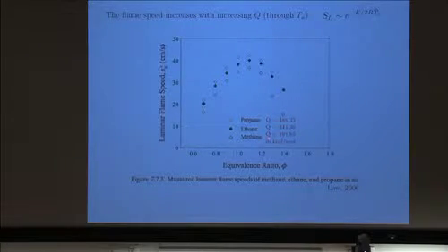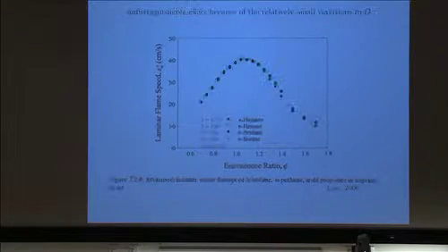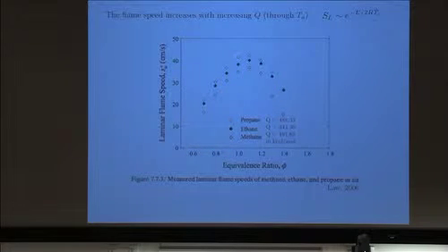What I want to show you is that since the heat release changes quite a bit from methane to ethane to propane, in fact, it's almost double here, and well, 40%, and then it's another 40 or 50%. Then clearly, the larger heat release will have a faster flame speed, and that's what this picture shows. But by the way, those are measurements, right? Those are flame speed measurements as a function of equivalence ratio.